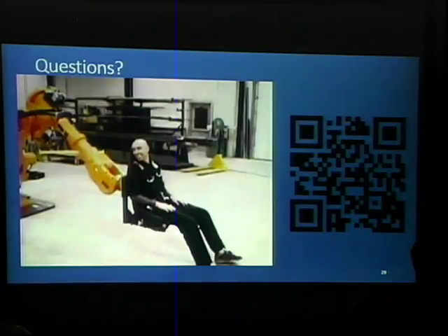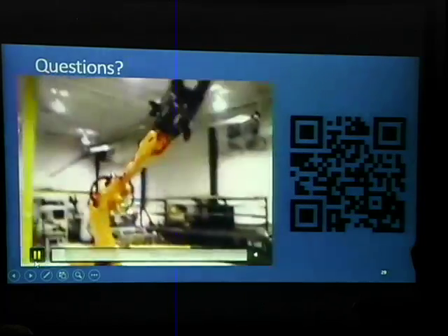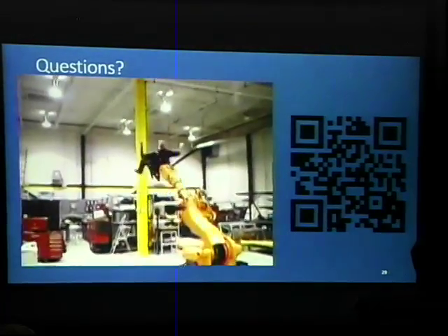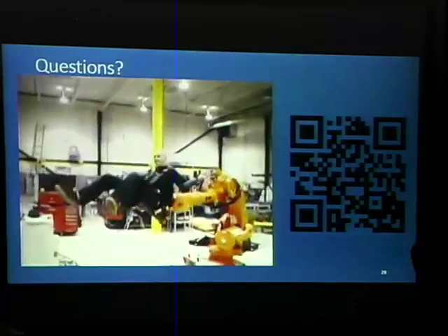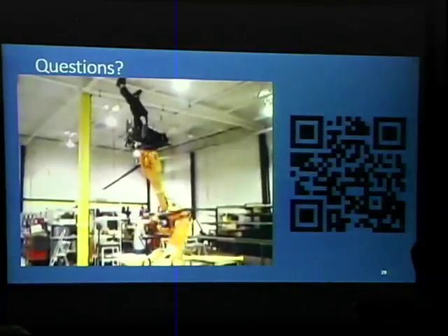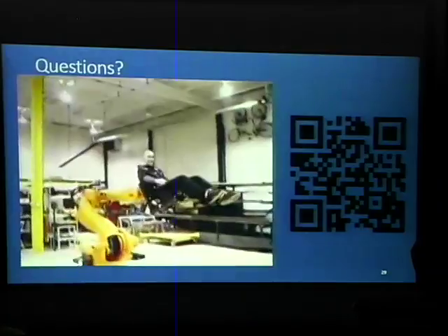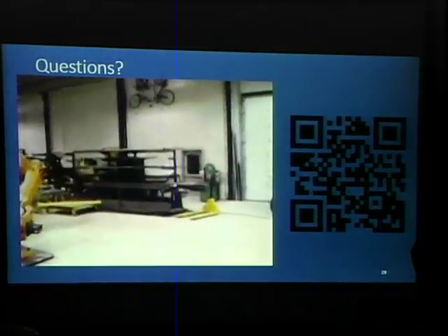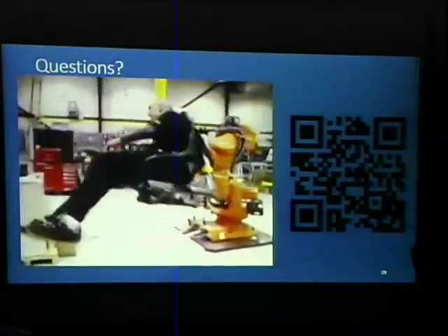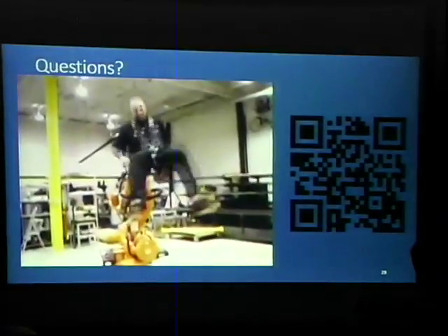Additionally, when you actually run the machine, you're able to watch on the CNC controller screen what different commands are going by. And if you can identify where there's an issue or a glitch, you're able to go back and fix that. One of the common things that can happen is, when people start to learn about this, they're always asked to write a program to drill 2 holes in a piece of material. And if we mime that out, it's go to the location of the first hole, drill the first hole, and then what? Go up. A lot of people forget the go up part.